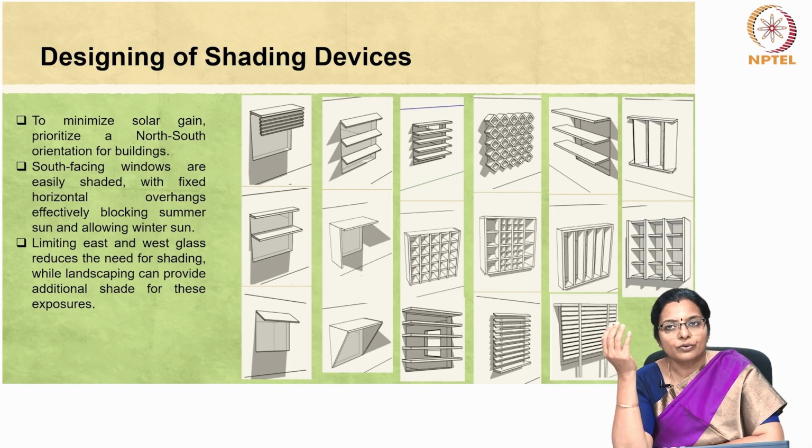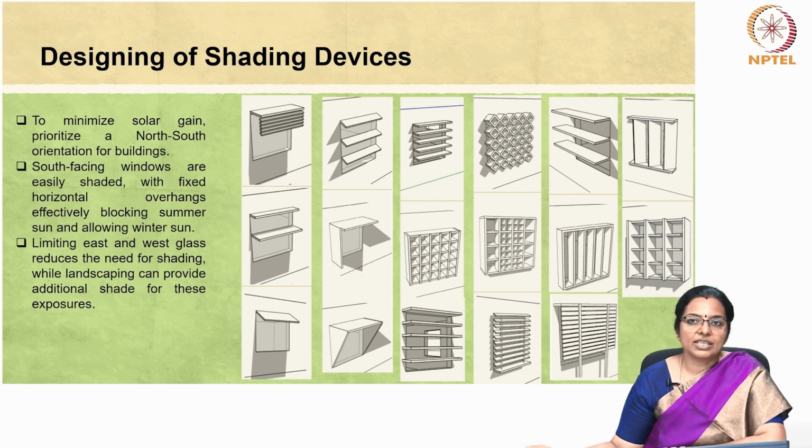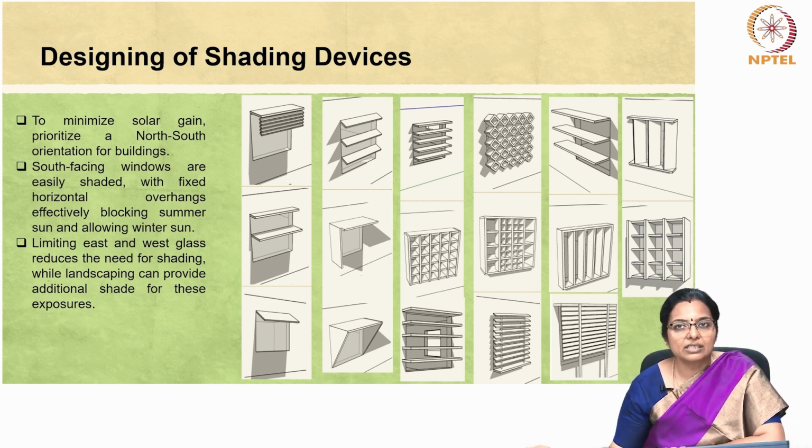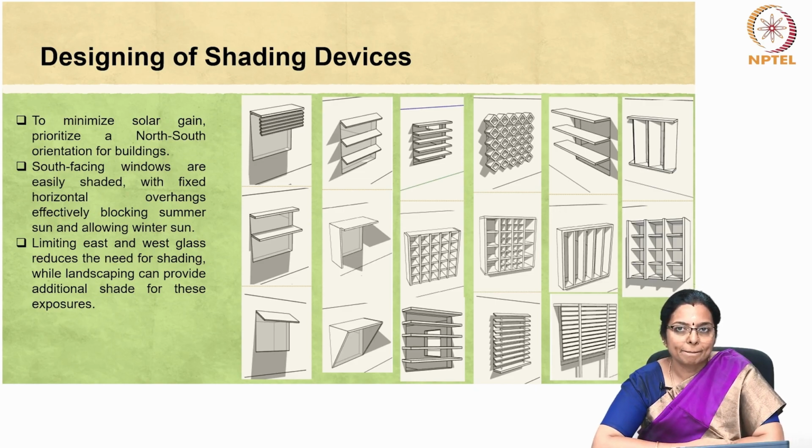An extended roof can provide shade to the entire north and south wall from the noon sun. Shading generally is not required on the north side as much as it is required on the other sides. Only cutting the low evening summer sun can be achieved by vertical shades or internal blinds. On lower buildings, well placed deciduous trees on the east and west will reduce summer overheating while permitting desirable winter solar gains in the cold part of the country.